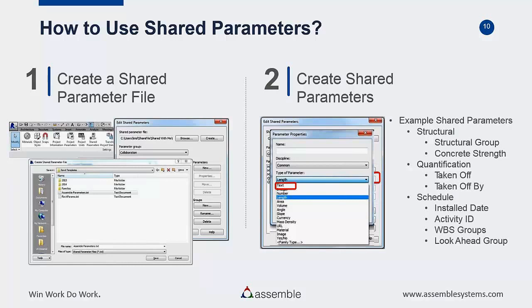You heard me talk about sometimes we were changing the concrete strength from the design model. So our modelers had followed the plans and they had modeled everything per the design, but we realized we were going to bump up the concrete strength on some of the floors, on some of the columns, on some of the areas. So we needed the estimators to have the ability to change that parameter.